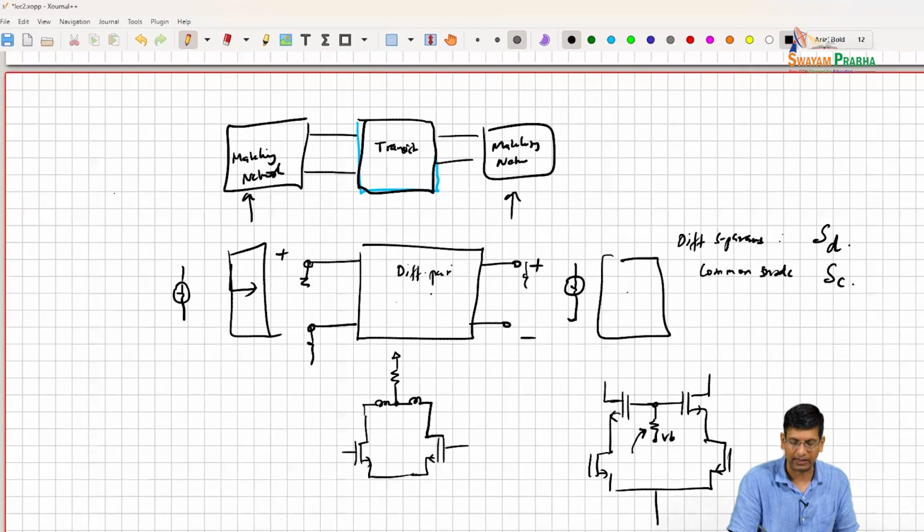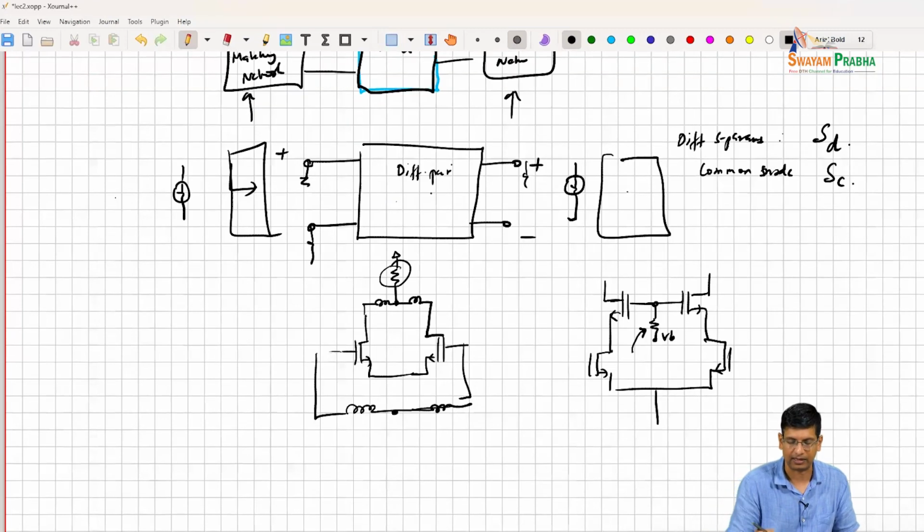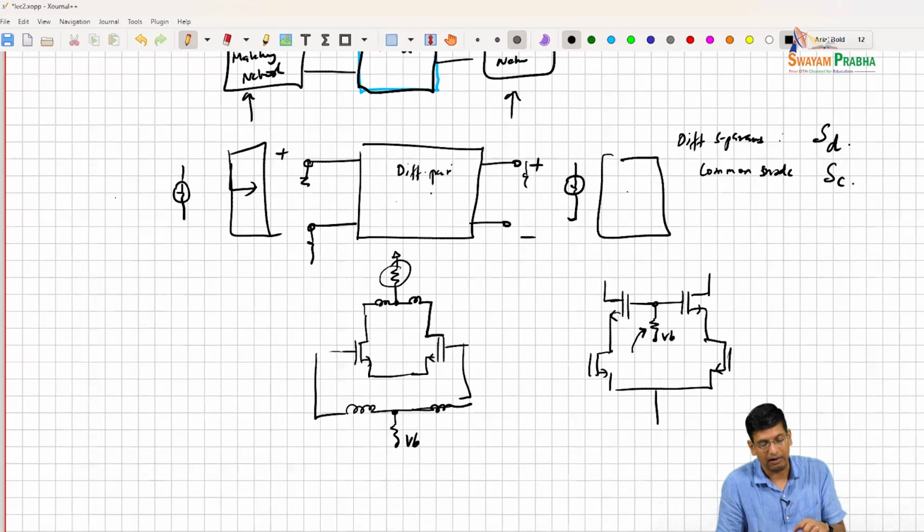Similarly, I might choose to introduce this resistance here, or in the scenario where at my input I have a differential inductor and this common mode point, I put a resistor to bias it. I can make my network for common mode and differential different to introduce stability, but that implicitly says that in common mode you are trying to introduce some loss in your system.